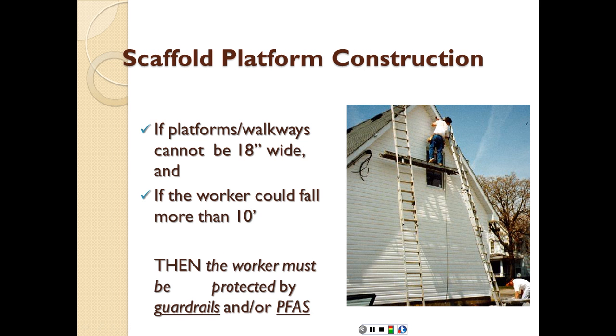Now here we have, how would you classify this? Would this be a platform scaffold? It's definitely not a suspended scaffold. Here we have several violations, by the way. No fall protection whatsoever, very narrow scaffold not properly erected, no hard hat. So again, several violations in this picture on its own.